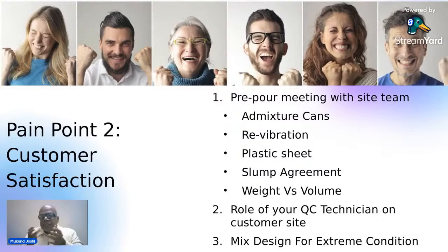So once you tell him that this is the requirement of concrete, not you as a RMC supplier, your 90% problems would go away. First one, no cracking. Second one, the concrete which is revibrated will have such a nice strength that even if somebody does NDT on that concrete due to whatever failure of cube, something wrong happening, you will be rest assured that concrete will show far better strengths due to revibration. So that point number 2 has to be in your minutes of meeting, of pre-pour meeting.